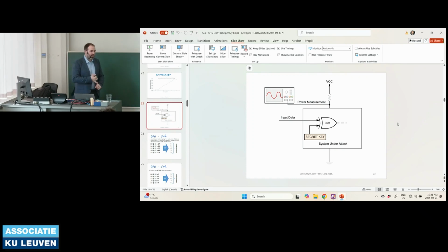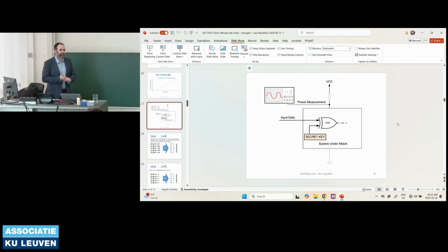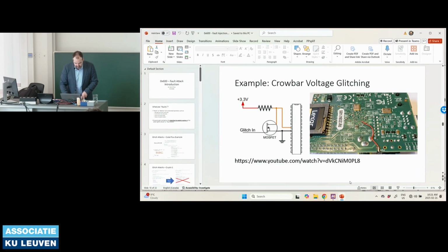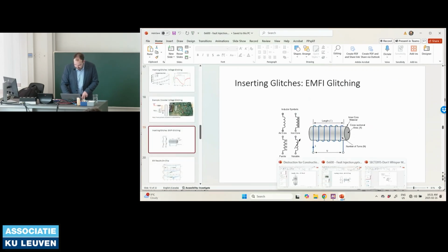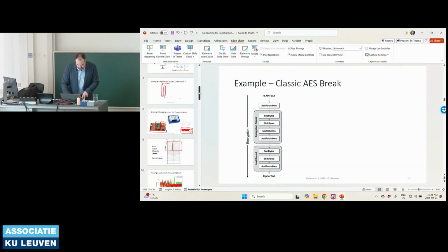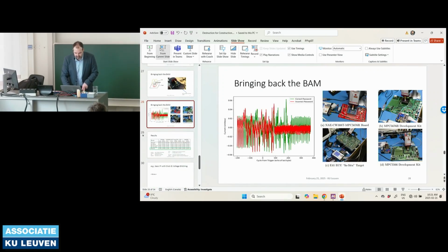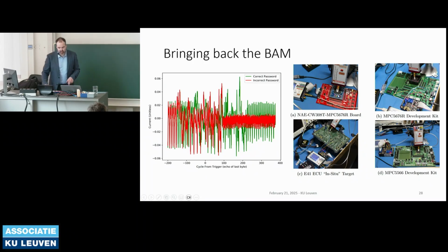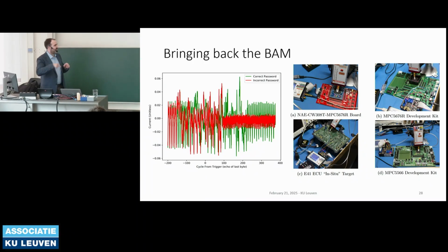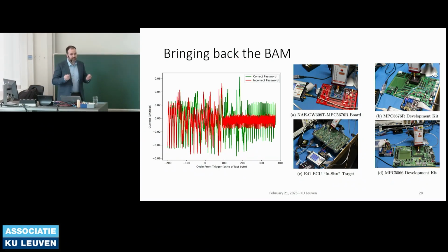In real life, you can just use power analysis. Most microcontrollers have some sort of obvious boot up, either over serial, or in the case of the automotive one, this automotive microcontroller has a reset out pin, and it actually asserts that reset when it goes into a reset state. So you can also use that. Not all have that. That's less common, that you'd be so lucky. But it's a pretty easy problem to solve.